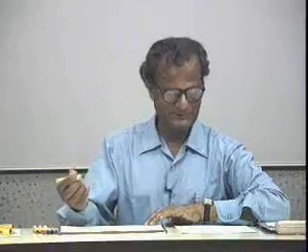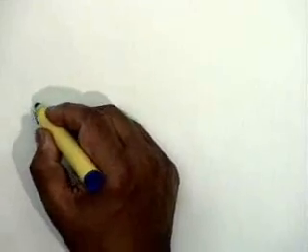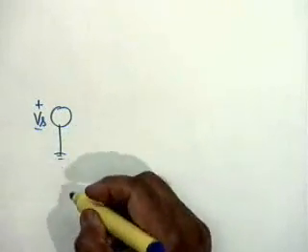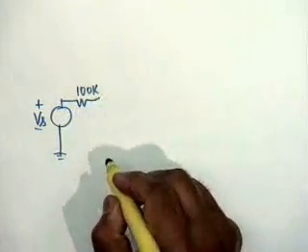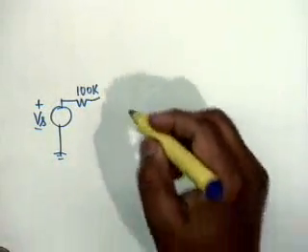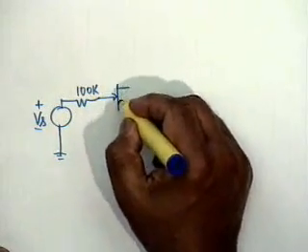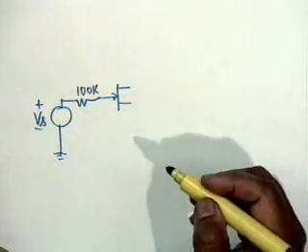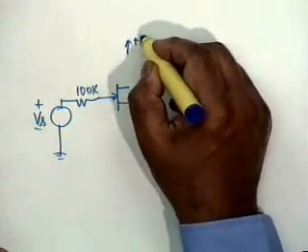The first problem that we tackle, these problems are on feedback amplifiers. The first problem is the following. We have a source Vs. I have chosen 4 problems to illustrate the 4 different kinds of feedback architecture. The source resistance is 100K, and to bring variety into experience, we have a FET, FET goes to plus 15 volts,